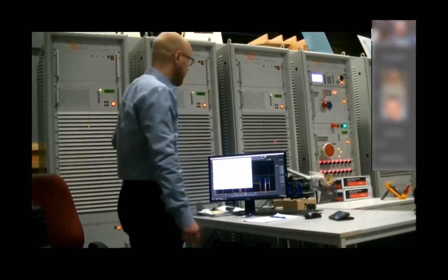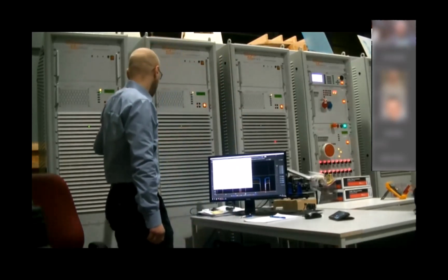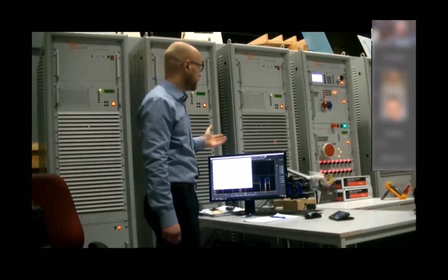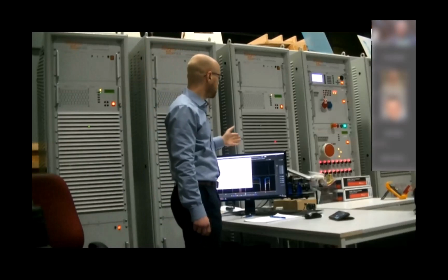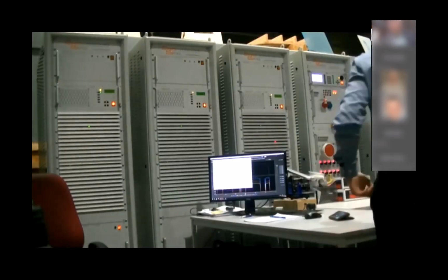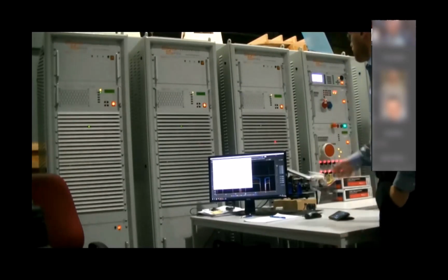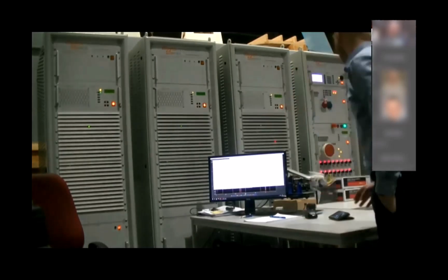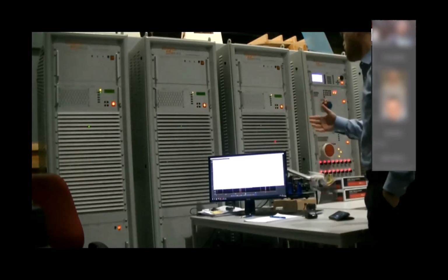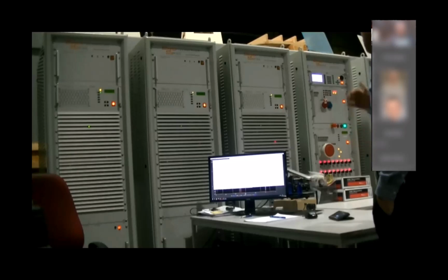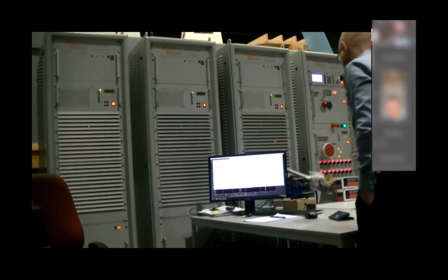And each amplifier has a power of 15 kilowatts. So in sum, we have 54 kilowatts that we can simulate or create. And we have a surface for this AC power supply where we can manipulate the waveforms in such a way that we can give them harmonics, we can say we have unbalances, we can do voltage steps, frequency changes, and so on.